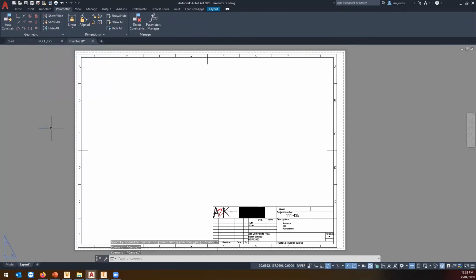Now, there's a tiny little bit of pre-work to do in here. I've done this pre-work. Basically, you need to set your template up correctly for it to look correct. It's not to make it work correctly, it's just to make it look correct. And that's mainly for your styles, for the layers. You may want your hidden lines to be red, or gray, or magenta, and you want your visible lines to be a different color, or even a different thickness.